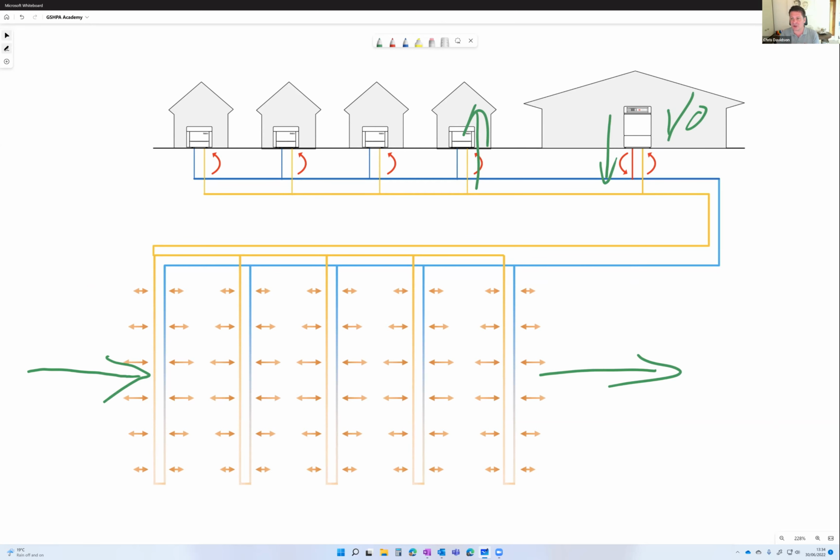So provided we know enough about the profile of those loads in the building, then we can design that heat network to be sustainable without any real control over that central infrastructure. So that's the benefit of ground source, particularly when we're talking about mixed loads.